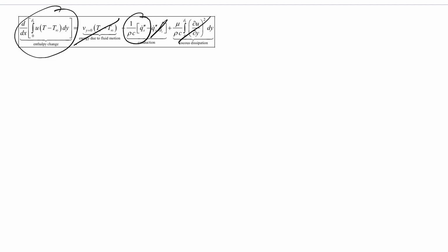Okay, so then what are we going to assume? So let's assume for our temperature distribution, just to be consistent with the velocity assumption that we did, let's again assume it's a second order polynomial, go through the same analysis. You don't have to make that assumption. You can make it more complicated if you want to. For our purposes, let's just do it that way.